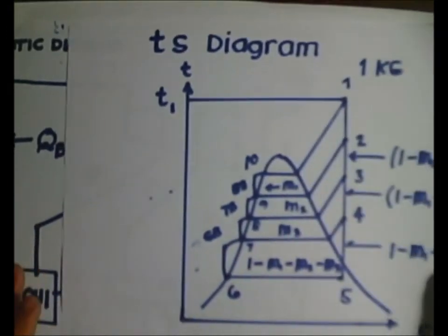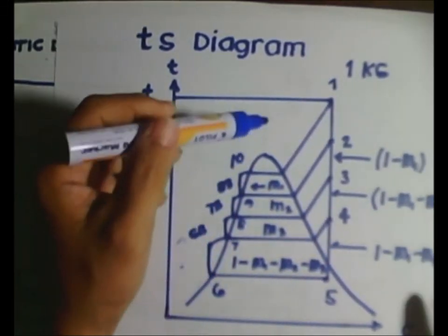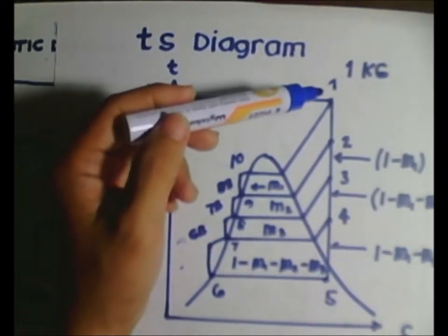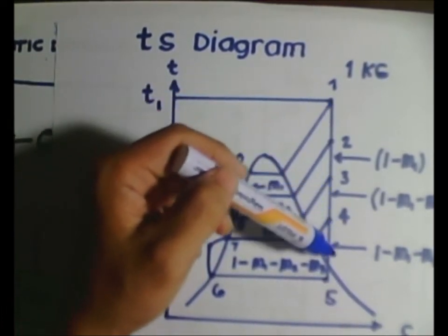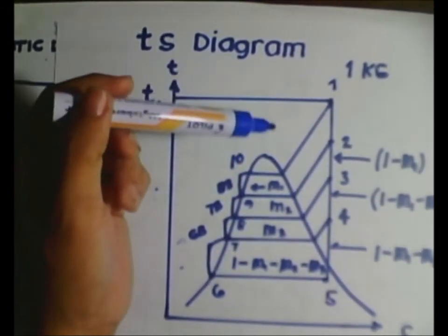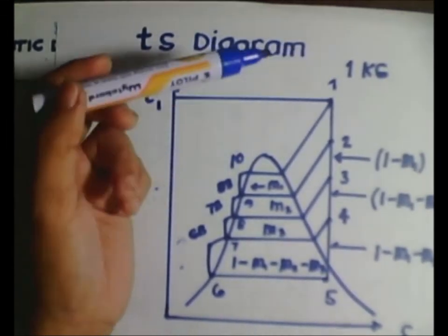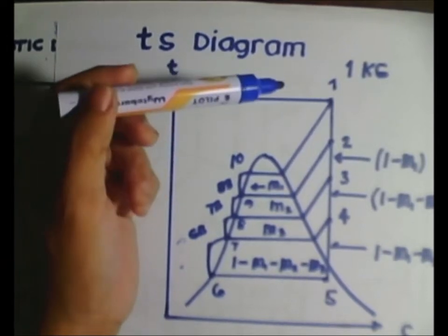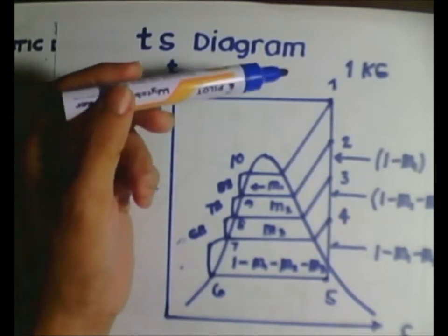By the way, these points here are governed by the steam properties, and the enthalpies that we need in order to calculate for the required quantities like the turbine work, the heat rejected, heat added to the boiler, pump works, are all taken from the steam tables, and we know how to determine those properties already.